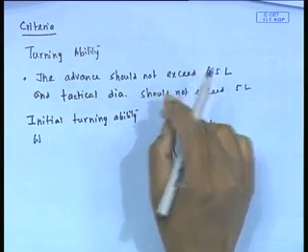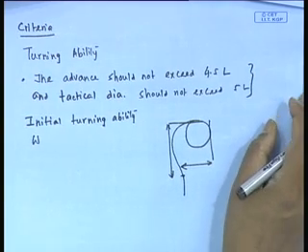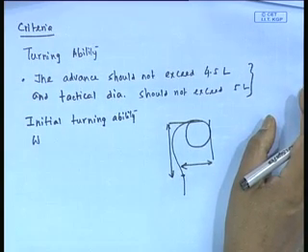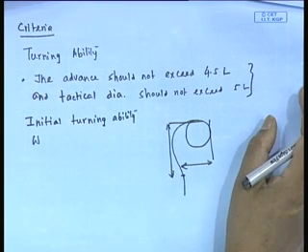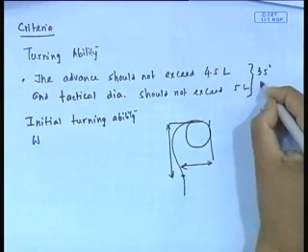This is very important. Turning circle is to be maneuvered with 35 degrees of rudder or maximum rudder angle permissible at test speed, following a steady approach with 0 yaw rate.